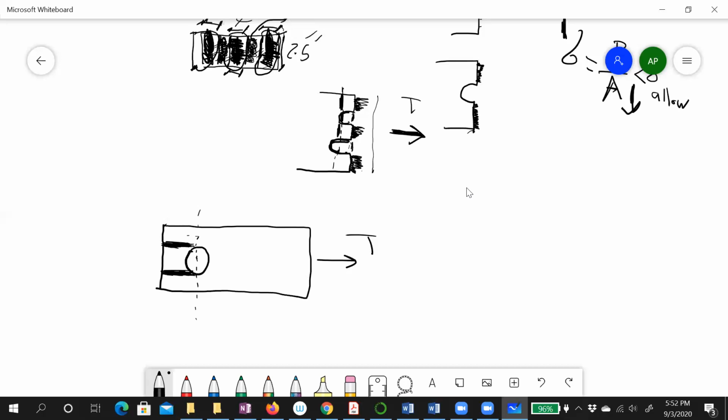The engineer, based on some force and the dimension, uses tables that say use the minimum value from the center of the bolt to the edge, and that minimum value is based on the diameter of the hole, right? So the reason behind those calculations is shear, this one.